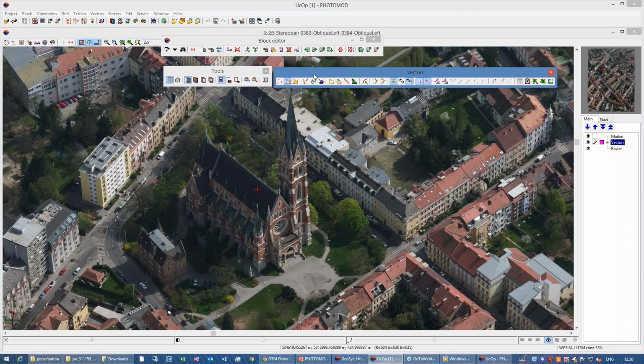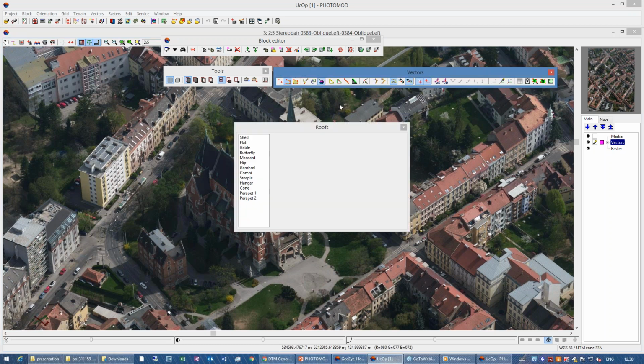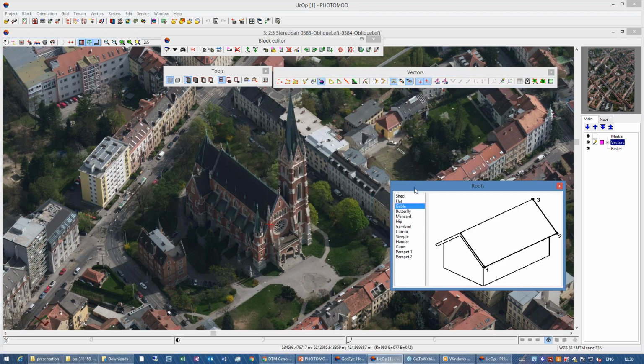And now I would like to show you how the new stereovectorization tools work. So firstly, we can create a new user coordinate system for aims of stereovectorization. For example, this direction will be the direction of the user coordinate system. In the bottom left corner, a new coordinate system appears. Then let me create a gable roof.